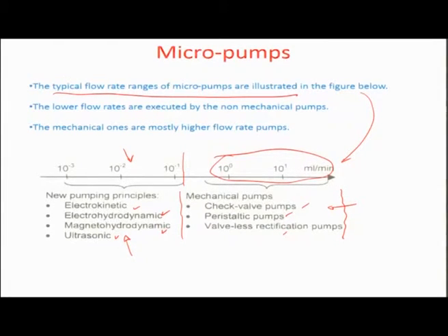But then what is the reason why such new pumping principles and such innovative actuation schemes are initiated? One of the major reasons is that in microfluidic flows, particularly when we are talking about applying these to human diagnostics, clinical diagnostics, etc., the volume is very low, and you have to have a very controlled motion of a very small amount of fluid within chip size platforms, so that they can have everything, including signal transduction, the recognition of the element, the signal readability aspects, the interpretation aspects in a very small area. So, therefore, the energy needed for such movements of minuscule amounts of flow may be minimalistic, and mechanical pumps may not satisfy that kind of range of flow requirements.